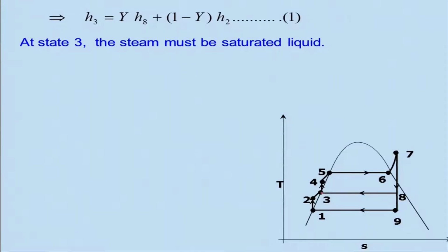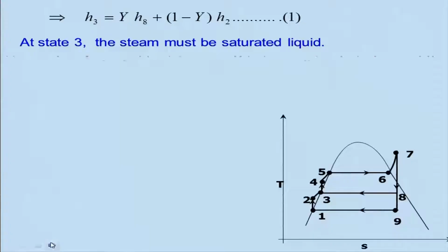Suppose instead of here, it is not coming here, it will become here. If you go for a closed feed water heater, then it will be problematic. Again, you will have to compress it, and two phase flow is difficult to compress. So, therefore, open feed water is advantageous than the closed feed water heater, right. But however, people do use both.